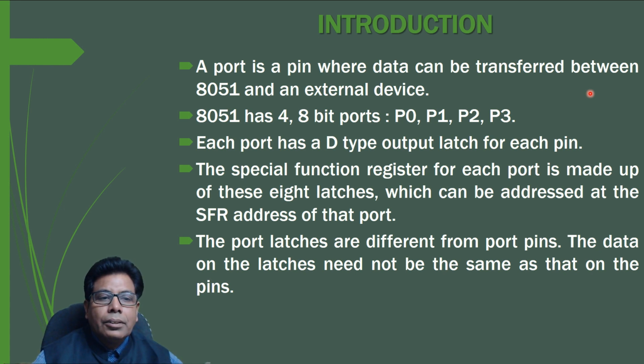So the SFRs are special function registers where the port address is available for the user, and the ports are directly addressable using that address. The port latches are different from port pins. The data on the latches need not be the same as that on the pins. So when we are working with the ports, we have to be careful.